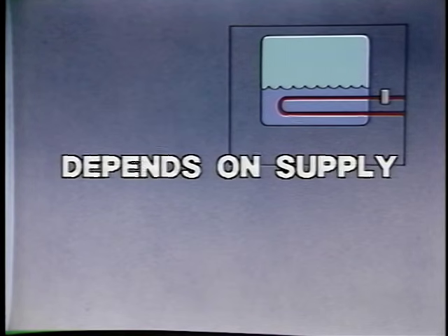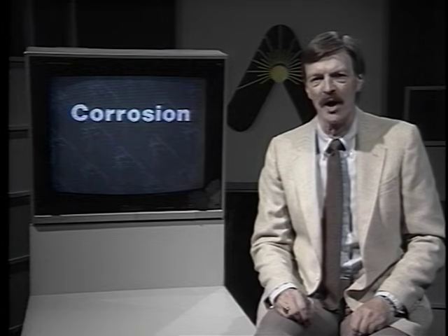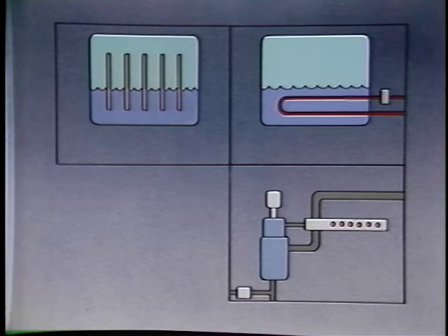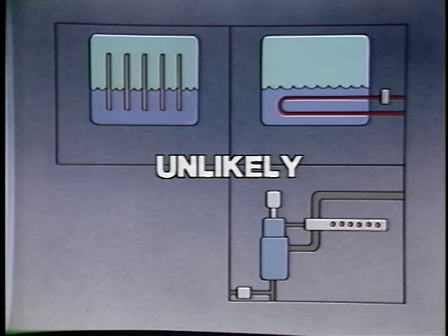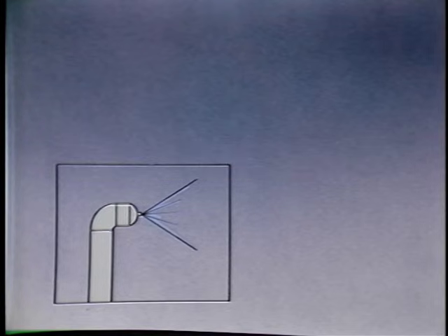Bacterial distribution from an evaporative pan system is dependent on water temperatures and treatment, as well as cleaning. Corrosion is likely in a humidification system whenever water is present as a liquid. Since the steam, evaporative pan, and wetted element methods discharge water vapor, the ductwork in a properly designed system should be free from corrosion. The reservoirs of the two standing liquid-based systems may have corrosion problems related to water quality. Every component of a water spray humidifier is susceptible to corrosion problems.